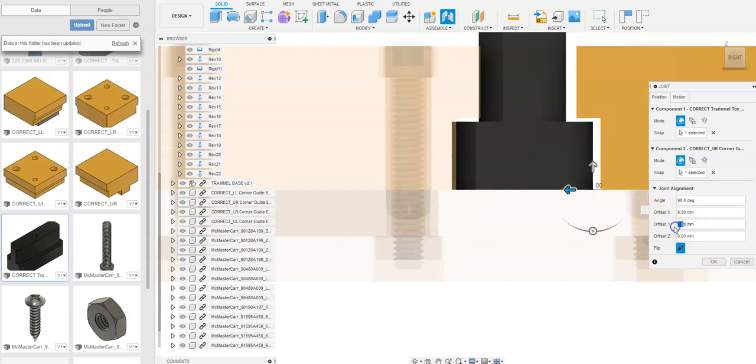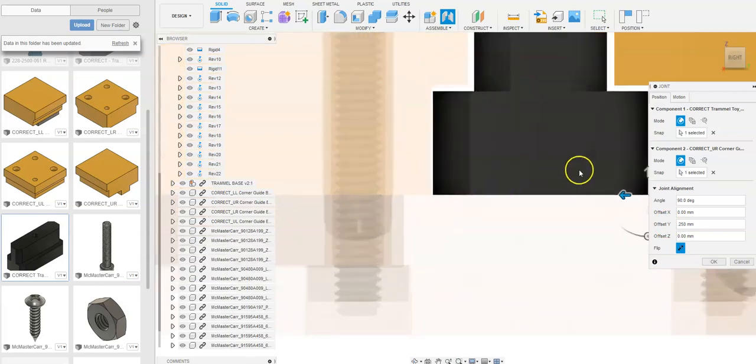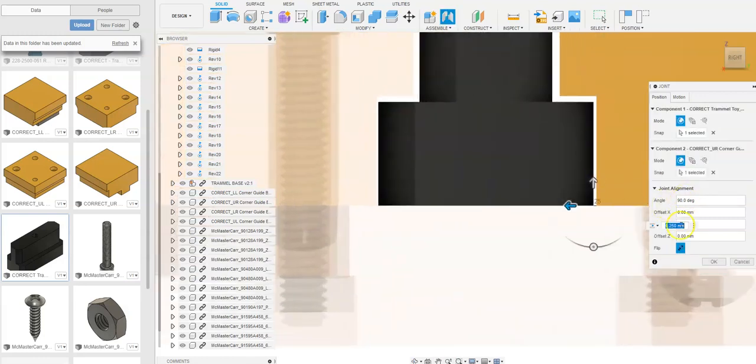I'm going to highlight in my y offset, and I'm going to say 0.25, and I want to see what that looks like. If that gives us a decent gap, we can always move in here. This looks a little too much. I'm going to take the 5 off, and I'm going to go 0.2, and we can kind of eyeball this a little bit. Maybe I'm going to go back and take away that 2 and go 0.15. I'm going to keep this here just like that. 0.15 seems to give me a pretty decent gap on each side.